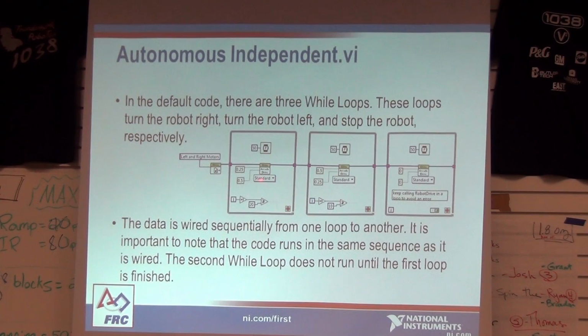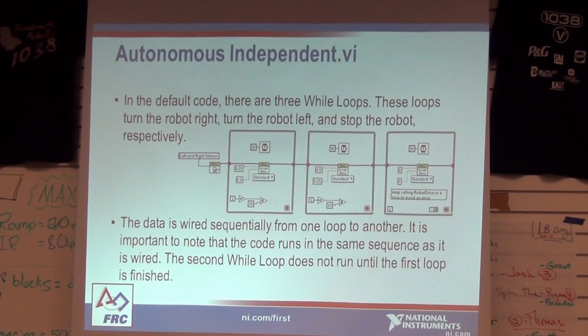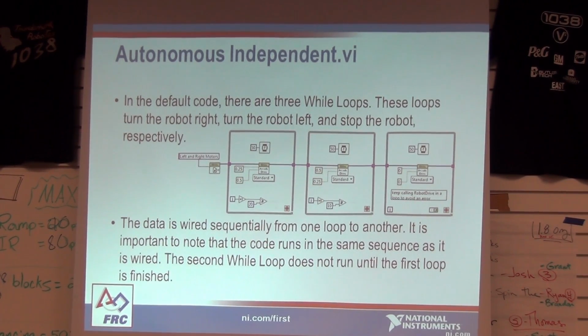If this VI executes longer than this 50 milliseconds, then this loop is going to run for longer than 50 milliseconds. It's going to continue to execute this VI. This wait is not going to stop it from executing. Now, if I were to use that timed structure, that would change, because then I'm setting the loop to run deterministically at a certain rate.